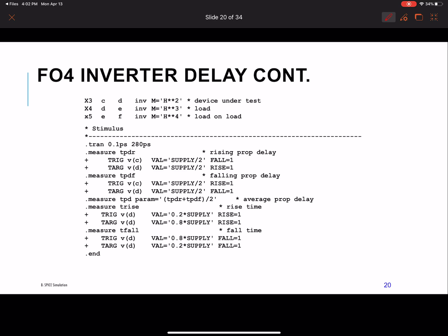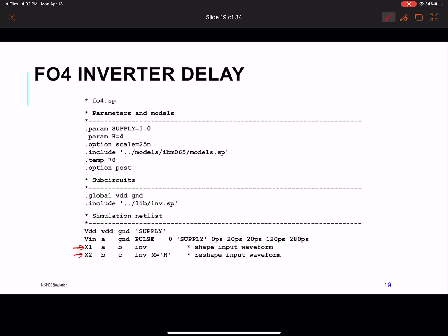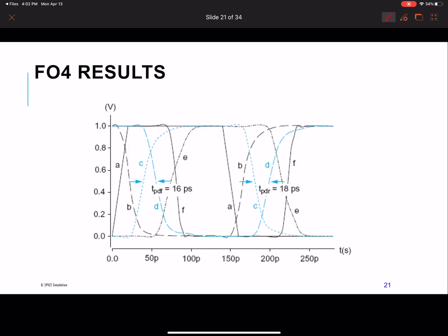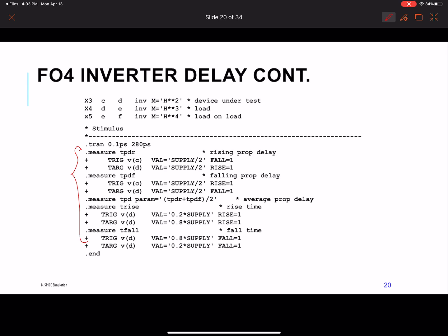And this is basically some measurement parameters. This is kind of a nice thing because you can set this up in the netlist to automatically measure, let's say, rise and fall times, etc., parametrically, and you can do sweeps and stuff like that. I'm not really sure what LTSPICE will allow us to do, but definitely if you go play with the netlist, you can do this by hand.